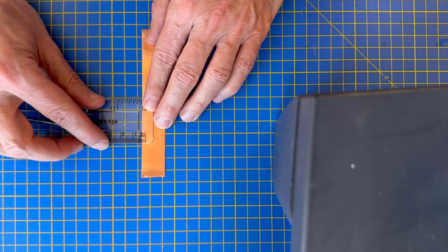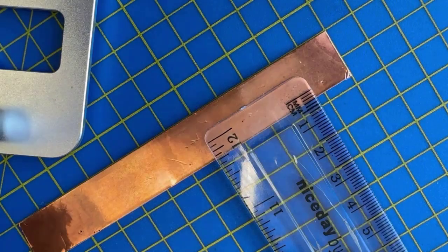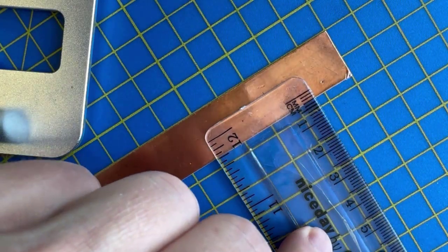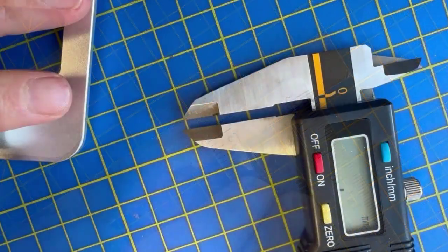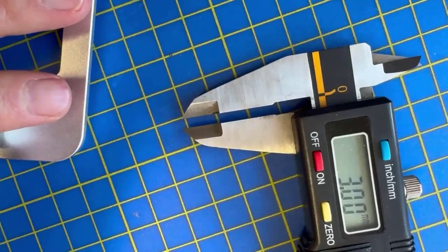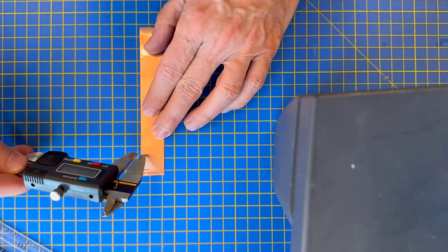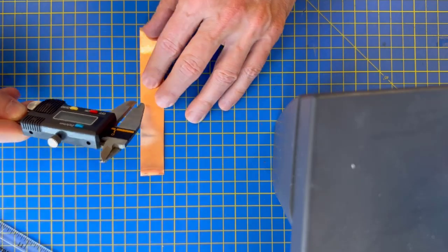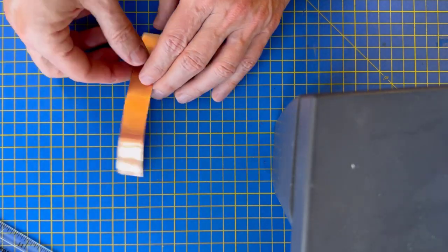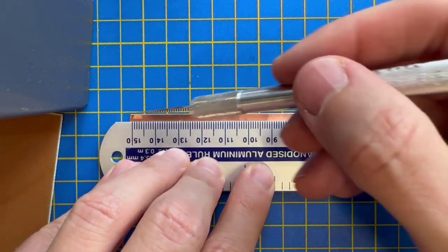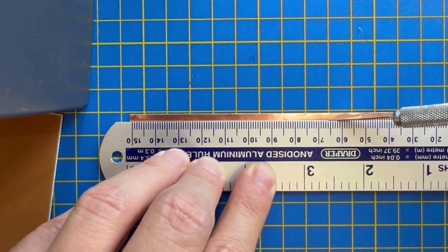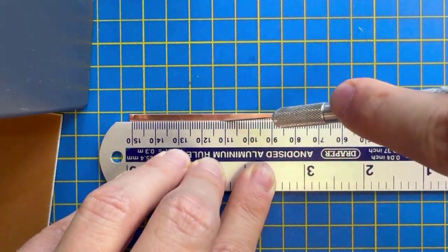You can do this by measuring 3 mm with a ruler at two different points and marking those points on the strip. Or you can use a caliper. Open it to 3 mm and then use it to mark 2 or 3 points, 3 mm away from the edge of the strip. Next, use a knife to cut the strip. Make sure that you take precautions to prevent injuries.